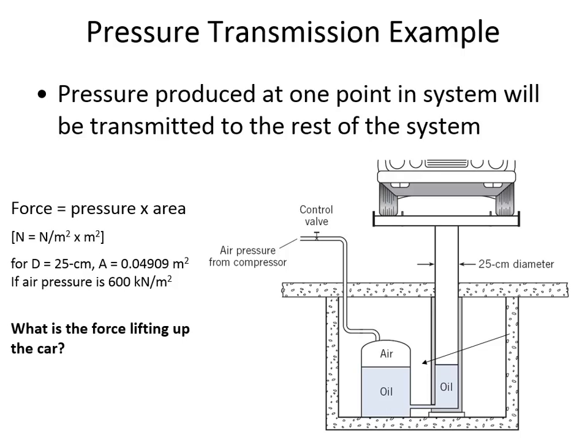Yeah, it is sort of like an equilibrium situation. We're in equilibrium right now, as pictured, with it being 600 kPa. So if we put more pressure, it's temporarily not in equilibrium. So it's in equilibrium right now. Right now, you've got the weight of the car plus cylinder acting down, and then you've got this pressure.